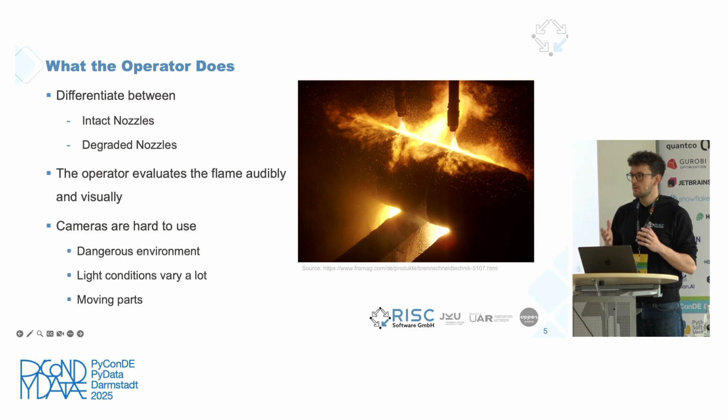Normally you would use a saw, however a saw can only cut material up to like 30 centimeters. Everything above that is really specialized and hard to do. And if the material is moving, like here, it's super hard to do. Instead you use a big flamethrower basically with a concentrated flame to cut through the material instead,